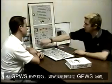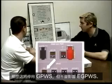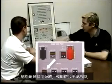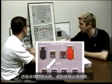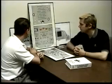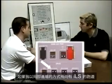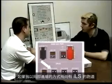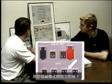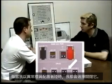If I selected the GPWS system switch off, then that will deactivate GPWS, but it does not affect eGPWS. By selecting the system off, or even if I have a fault, I don't get any modes of GPWS at all. When would you select glide slope mode to off? If I were flying a localizer approach to a runway that had an ILS where the ILS was either out of service or unreliable. What about the flap mode to off? Anytime I was landing in an abnormal flap configuration, I'd select that off.